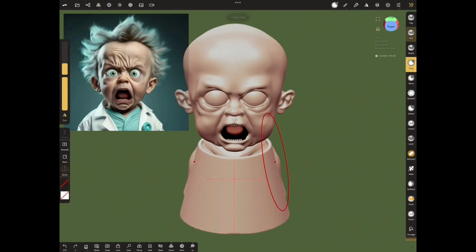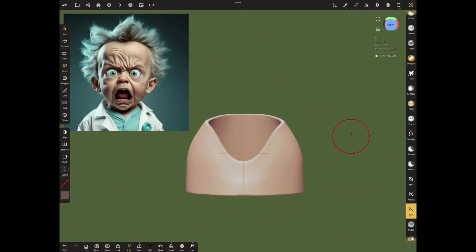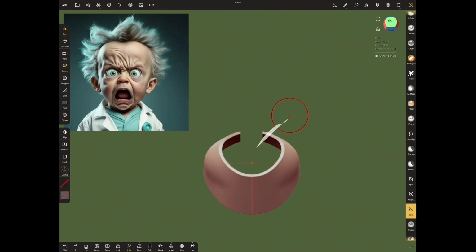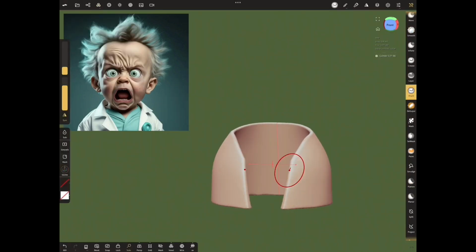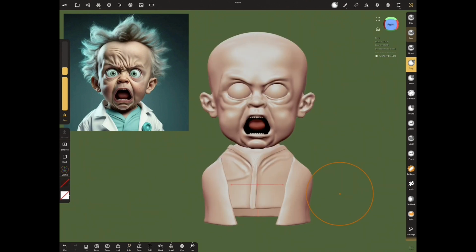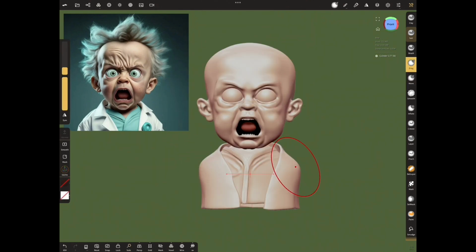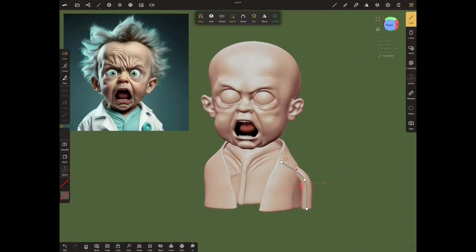After adding a cylinder for the white doctor apron, adjust it according to the body and cut the middle with the trim tool. After adjusting the apron according to its body using the drag tool, let's use the tube tool for the arms to place it on the sides as in the image, but do not validate the tube tool before the adjustments are finished.